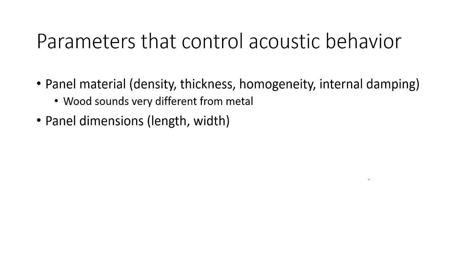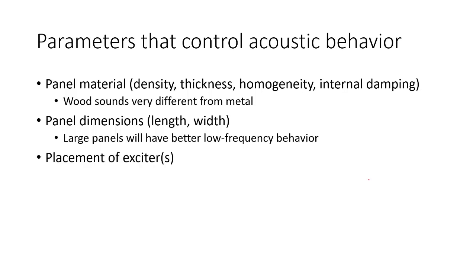The panel dimensions are also important. That's just the length and the width of the panel. A 1 centimeter by 1 centimeter panel obviously won't really sound like much of anything, but a 1 meter by 1 meter panel will produce a lot more sound. Large panels also are going to have much better low frequency behavior.